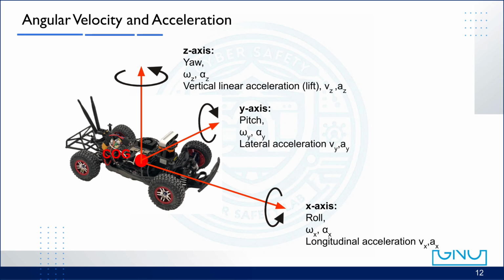We usually measure angular rates with the IMU gyroscopes and linear accelerations with accelerometers. Remember that accelerometers sense specific force, so gravity is included. We remove it by calibration or filtering. Use a consistent right-hand rule for axis directions, so the sign of roll, pitch, and yaw is unambiguous. Finally, note the link to control. Large lateral accelerations often correlate with large yaw rates, and roll and pitch transients tell us about weight transfer and grip. Interpreting these signals helps us diagnose understeer, oversteer, or poor damping.